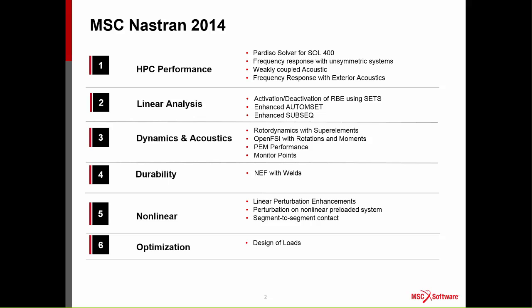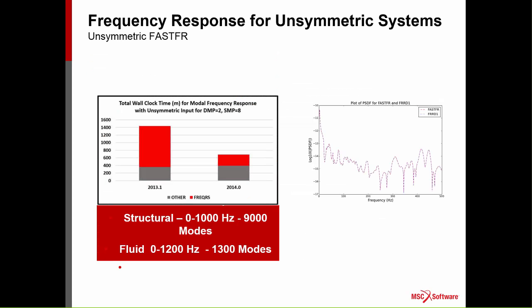solution sequence 400, enhancements to linear perturbation, and also the use of linear perturbation on nonlinear preloaded systems. Really, the objective in life is for Sol 400 to have all the capabilities associated with the linear solution sequences as well, or at least the most common ones, and some enhancements to segment contact. And finally, there was a capability to do optimization based upon a design of loads. So I can't talk about all those, but I'll just quickly go through high-performance computing, because that's also a theme